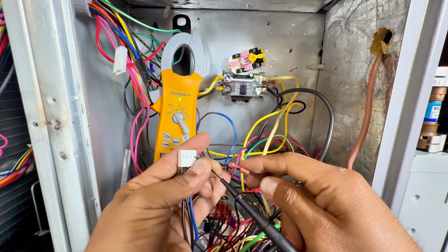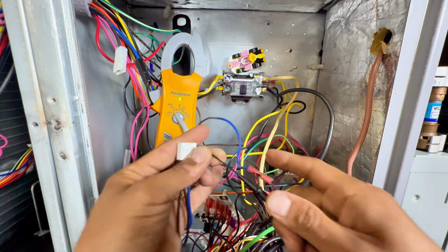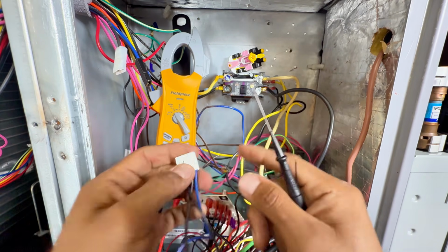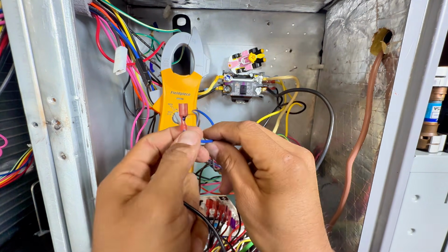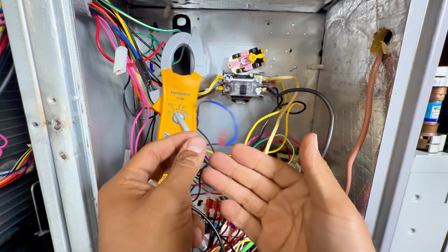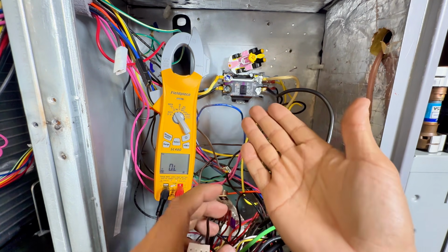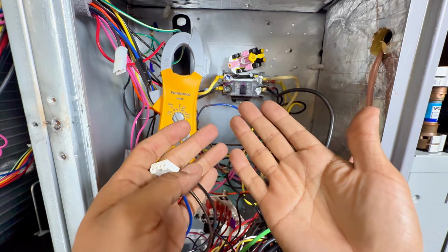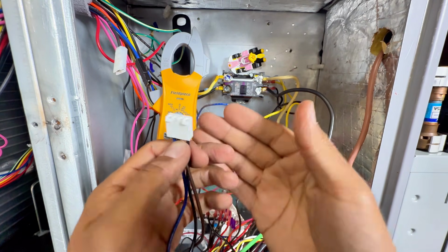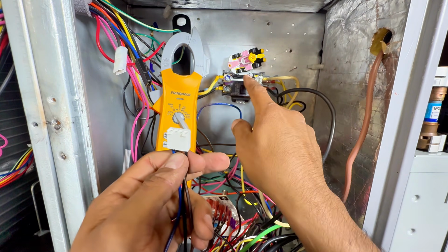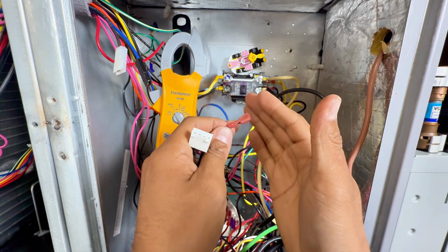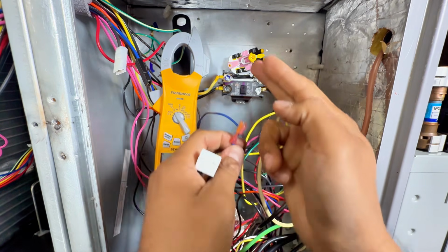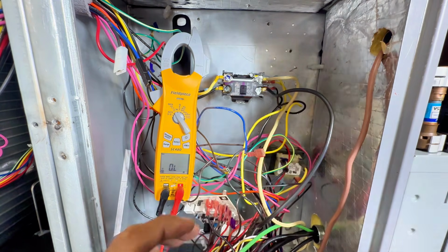So even though, let's say, the board sends out 24 volts through this wire to there, if this wire is bad, it's nicked, it's cut, it's never going to make it over here. So remember we said we need voltage, right? So we need potential difference. Commons are already there. If my wire is in good shape, then I'm going to have that potential difference, and then through the copper, I got current going back and forth. That can be one thing.